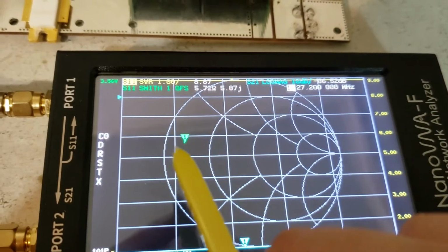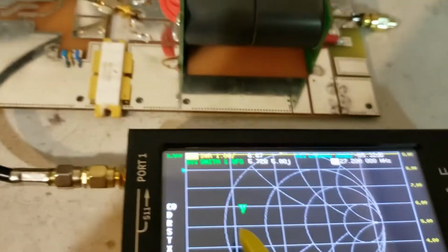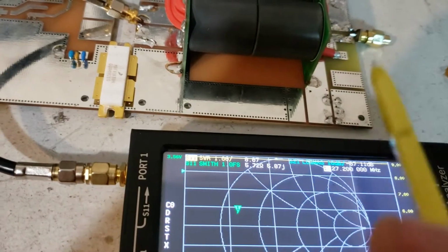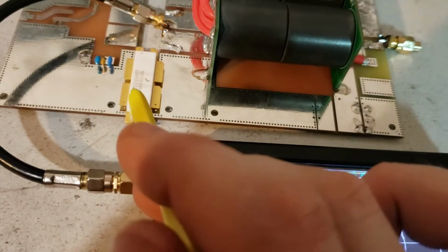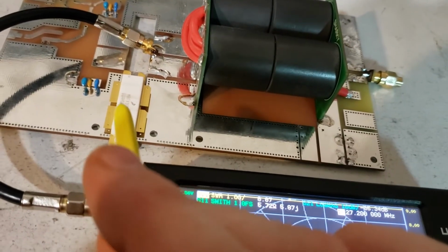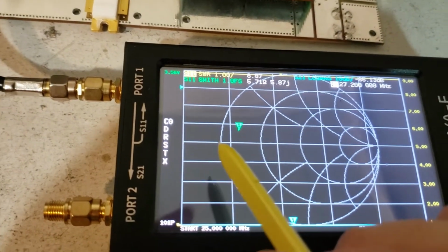So general rule of thumb, the lower the impedance, the more current your device is going to draw and the more power output you're going to get from your device. The higher the impedance, the less current draw you're going to get, and the lower the power output is going to be. Obviously, if you want more power, you're probably thinking, well, I should just go lower, lower, lower.